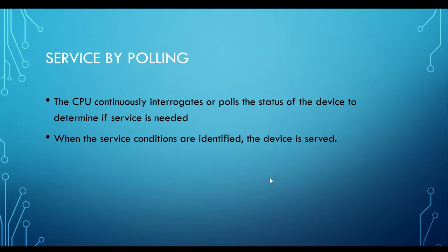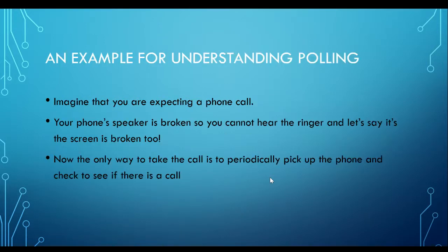In that case, you need to see whether that bit is 1 or 0, set or reset. Okay, vice versa for pins, peripherals that have reset values. Okay, so you need to program your CPU accordingly based on your peripheral, whether this device is a toggle, this device produces a set, or this device produces a reset.